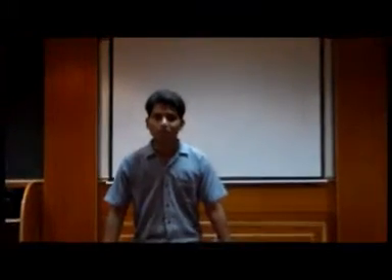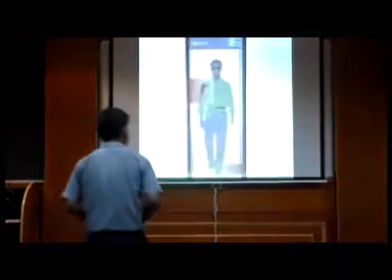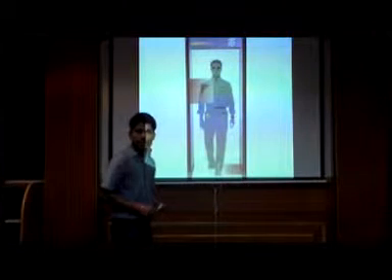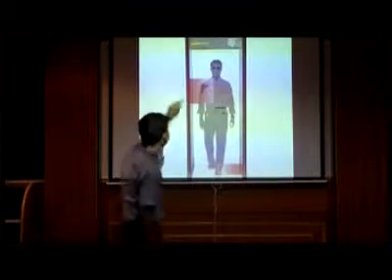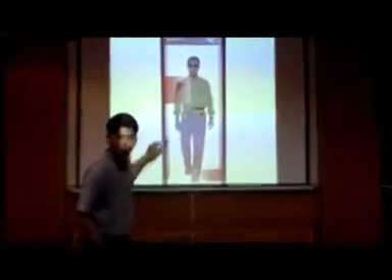So now let's understand what a metal detector is and how it works. A metal detector is a very useful electrical instrument that works on the principle of EMI and is used to detect metals. Now let's understand how it works in a very simple manner. A metal detector consists of an oscillator producing an alternating current that passes through this coil, producing an alternating magnetic field.